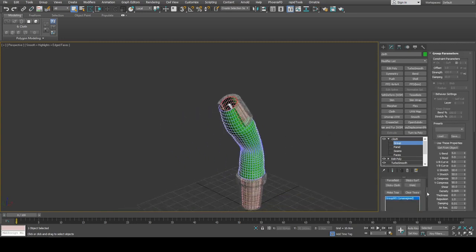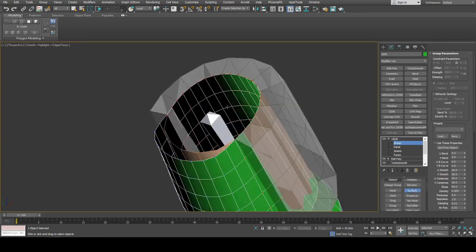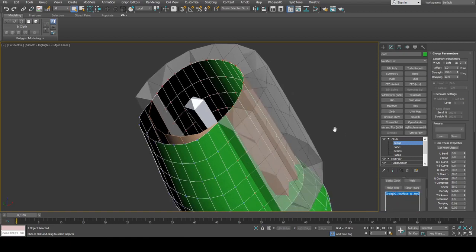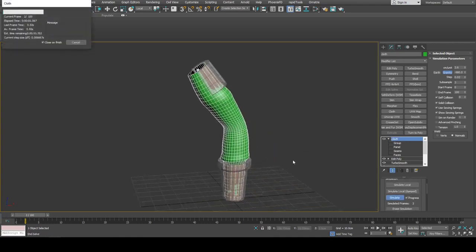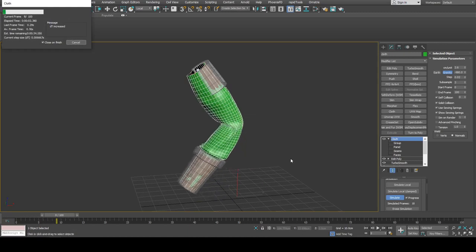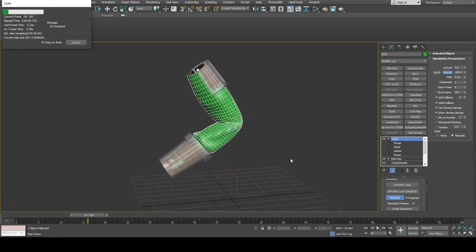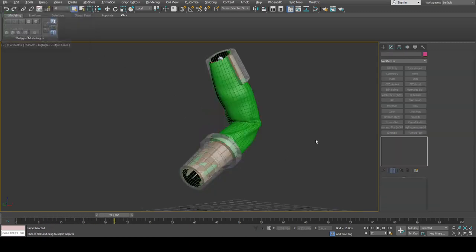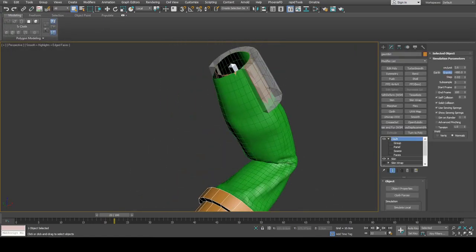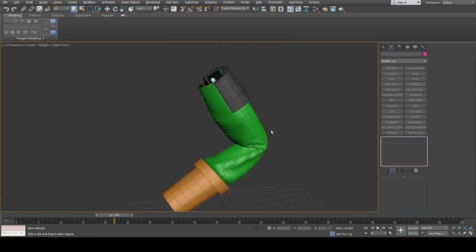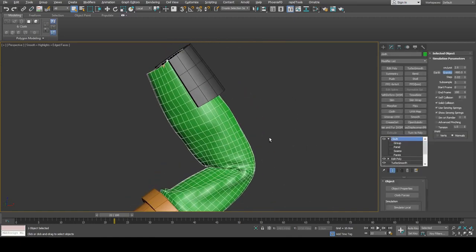You can also go down here and just rename this. I would choose surface again and click on the arm. And you can see if you scroll down here, it says group 001 surface to arm. All right, there we go. And let's re-simulate. Alright, so now it's looking much cleaner here. So this has been an introduction to some basic cloth rigging. So even if you have cloth close together, you can still get a good result.